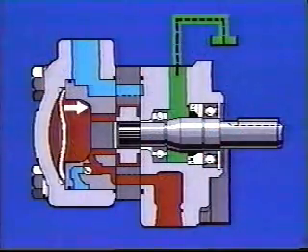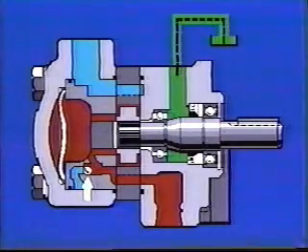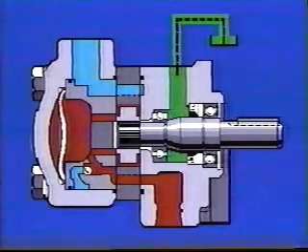It has a spring-loaded pressure plate. Oil, under pressure, coming in at the bottom port through a shuttle valve in the pressure plate allows us to pressurize the plate. This gives us the force we need to close up the running clearances. That same pressurized oil is also fed through holes in the pressure plate to the bottom of the vanes to help the rocker arm spring hold the vanes out.